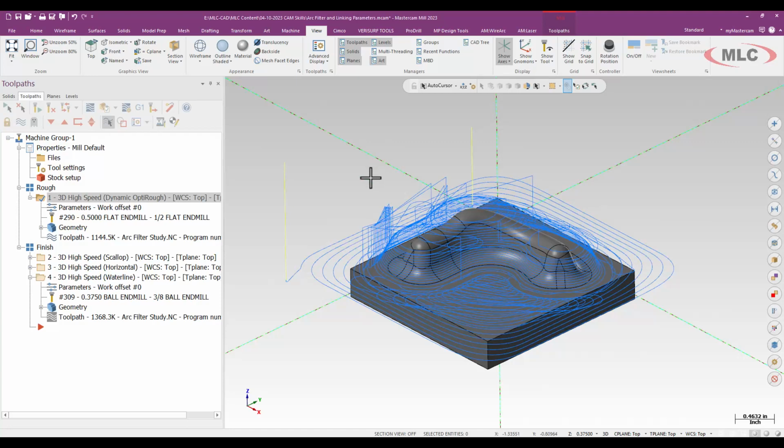So one of my favorite buttons in Mastercam is what is called the Advanced Toolpath Display button. And if you're not using this button, I highly recommend you do so. If I go ahead and click sort of on the pull down for Advanced Display, I can look at all the different types of toolpath motion I can see, and basically dictate each one of those as a different color. And the one I'm very interested in is the last one, what are called endpoints. Because when I view this toolpath with endpoints displayed, I may be in for a bit of a shock.